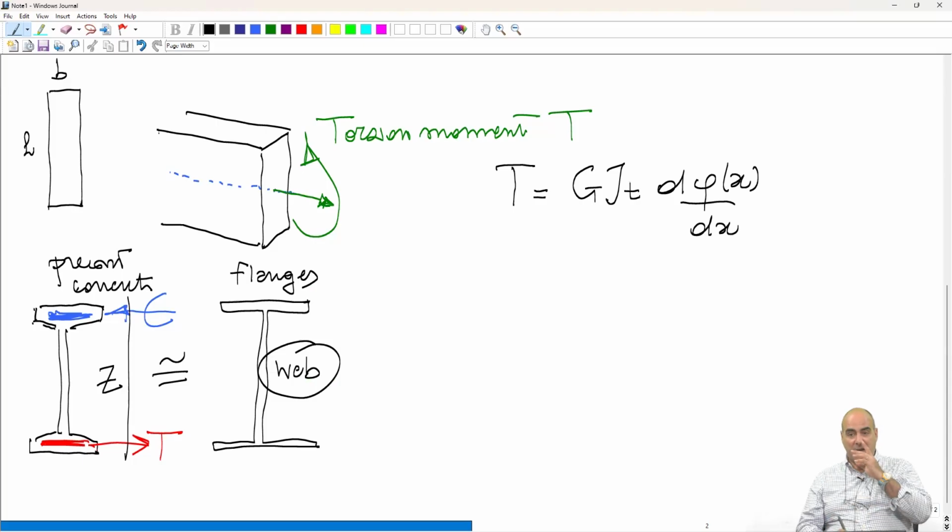As a matter of fact, for example, if you pick up typical steel beam geometries, the web carries about 90% of the shear, even more. And the two flanges carry around 85% of the bending moment. So in most cases, we simply say, okay, the flanges carry the bending moment and the web carries the shear. Well, this is a way to optimize, but there is another thing.